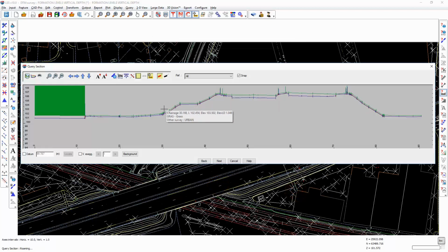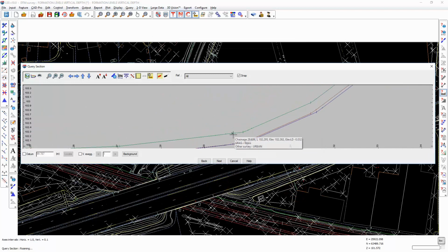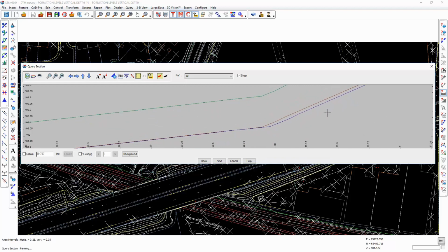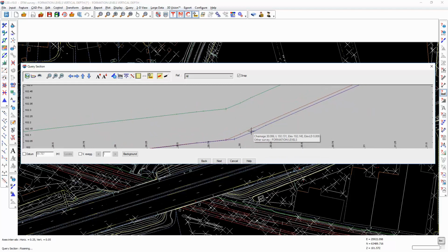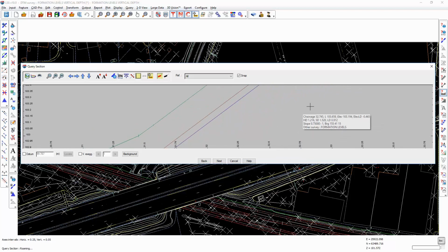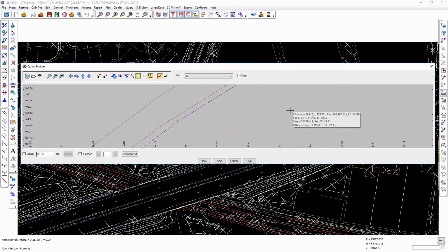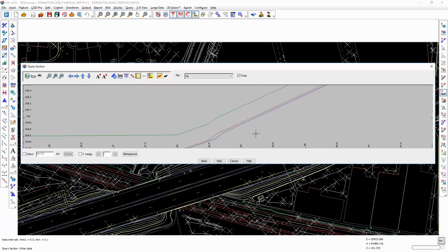If we just look at a small area of this, the green is the original ground level survey, blue is the perpendicular formation level offset, and red is the vertical offset. You can see the difference it has to the formation level depth calculation on steeply sloping areas. It has no effect in the flat areas.